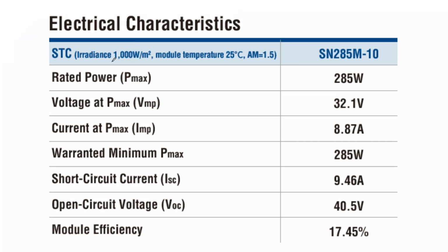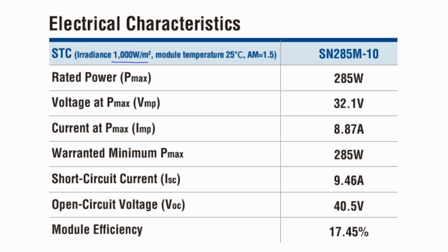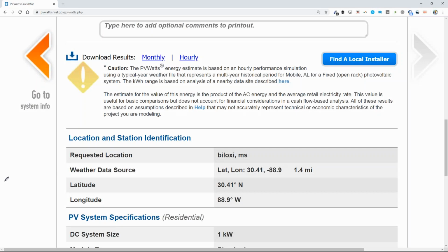And so that's why you can't just take a solar panel and say, okay, it's a 1,000-watt solar panel, the sun is up for 12 hours a day, and so 1,000 times 12 gives me how many watt hours the array produces. That's not how it works. There are shortcuts and fudge factor numbers for that. Even in the PVWatts interface,